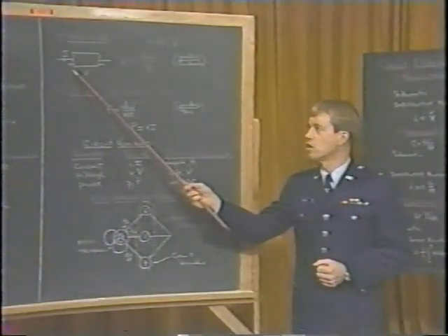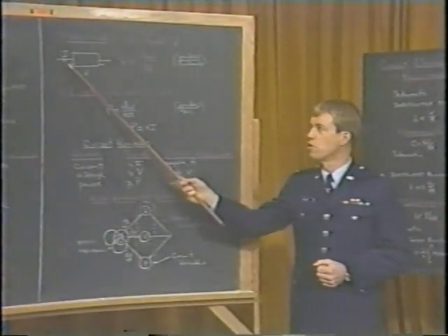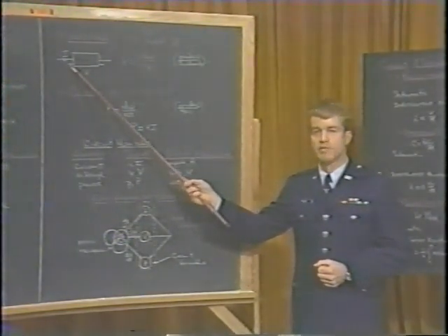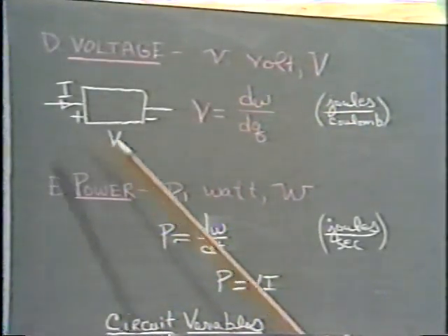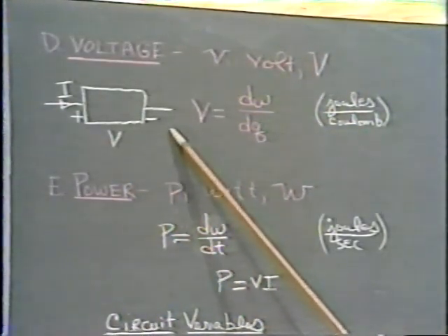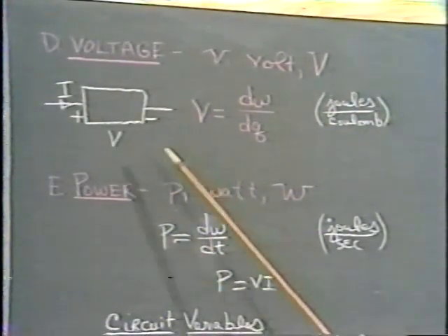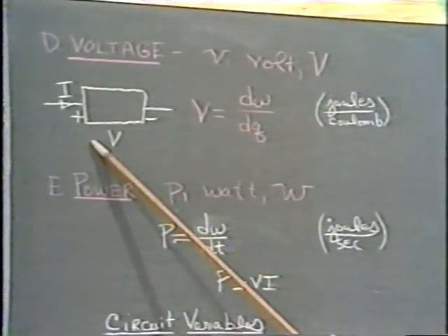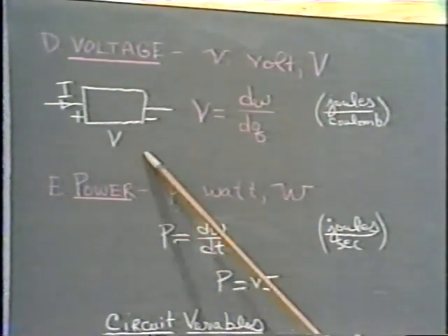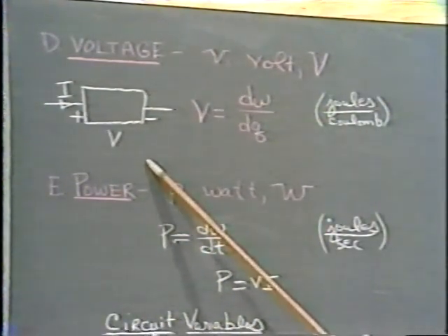Positive voltage will require that current go in to the positive terminal. This will be a voltage drop, and we will have to track the algebraic sign of the voltage. The opposite situation is a voltage rise associated with some kind of voltage or current source. And we'll define that as negative voltage. As I have it indicated here, this is a positive voltage, in the correct way that current should flow into a positive voltage.